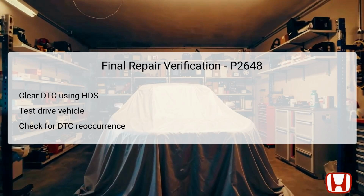After clearing the DTCs, taking the vehicle for a test drive is essential. This allows the system to operate under typical driving conditions and aids in validating that the repairs have resolved the issue. During or after the test drive, use the HDS again to check for any reoccurrence of DTC P2648. If the code does not reappear and vehicle performance is restored, the troubleshooting and repair process can be deemed successful. If the DTC resurfaces, further investigation into the wiring and connections should be performed, or additional components may need further attention.